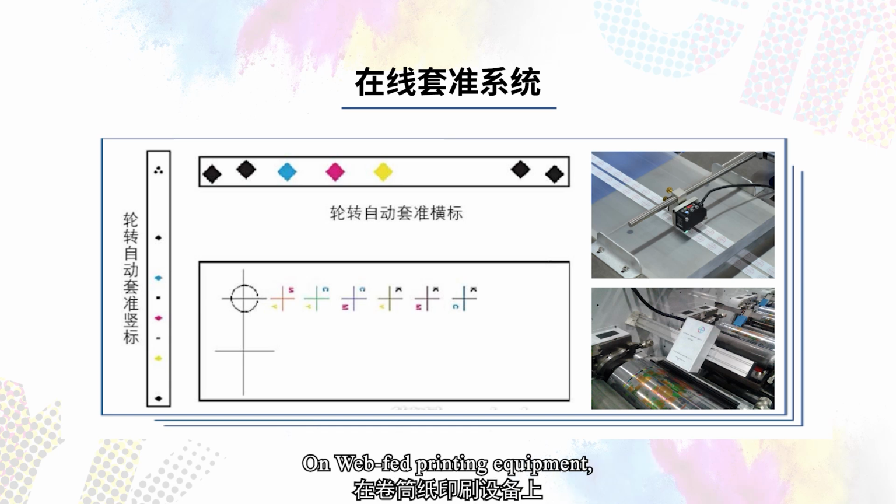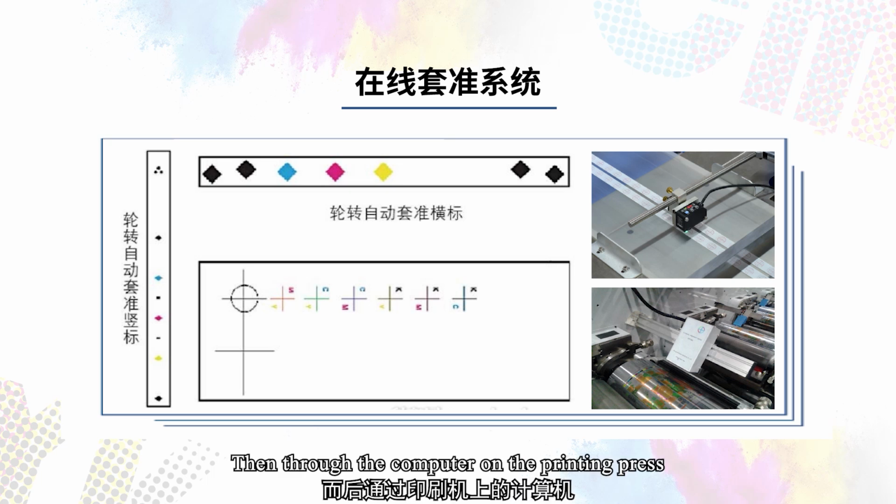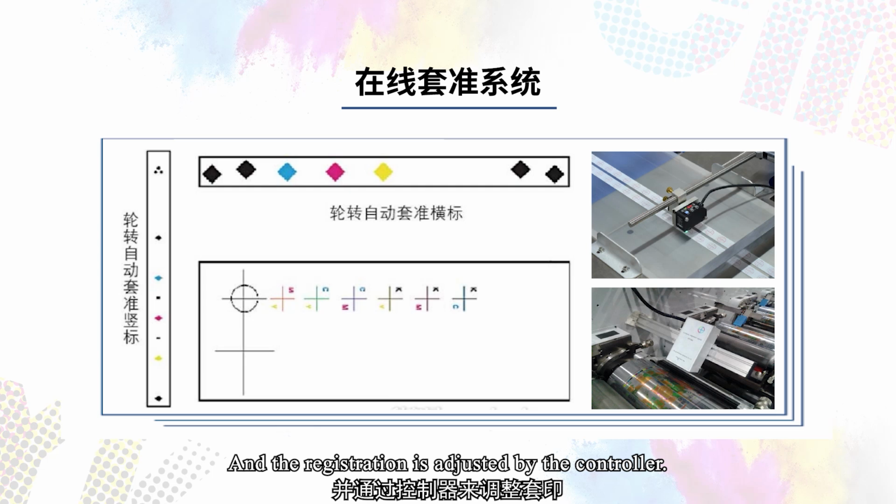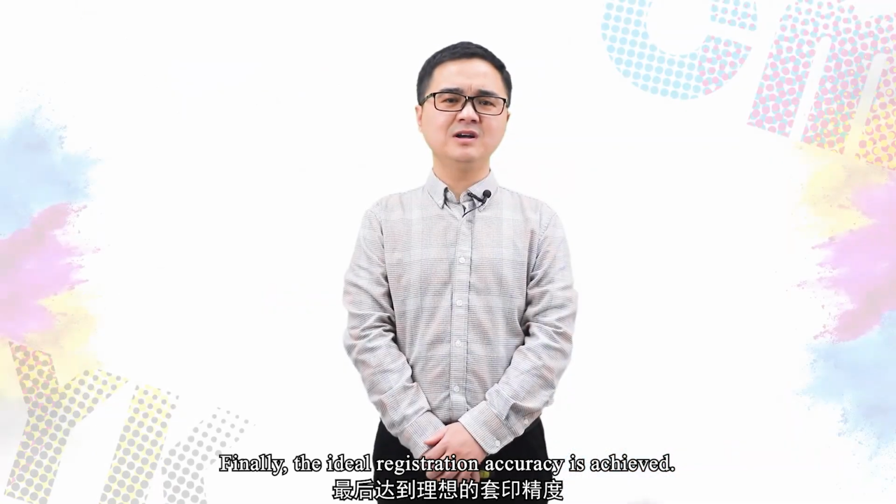On web-fed printing equipment, usually we use a camera to capture registration marks. Then, through the computer on the printing press, the registration error is calculated, and the registration is adjusted by the controller. Finally, the ideal registration accuracy is achieved.